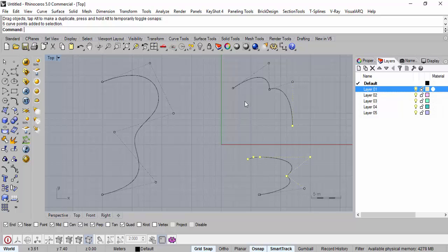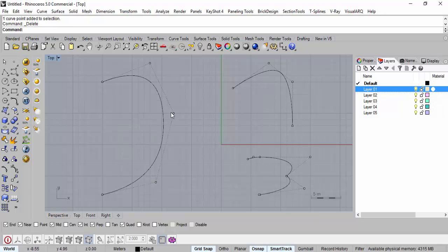You just delete this, and then you can delete these control points. For example, if I delete this control point, what would happen? Are you getting this? If I delete this one, it will take the next one, and the curve would be rounded off between the two points. Is this clear? Now, if you want to make this smoother, I can always come to control points here. Under this, I can insert a control point, and I can move my cursor along this. I have to select the object first, and I can move along this.